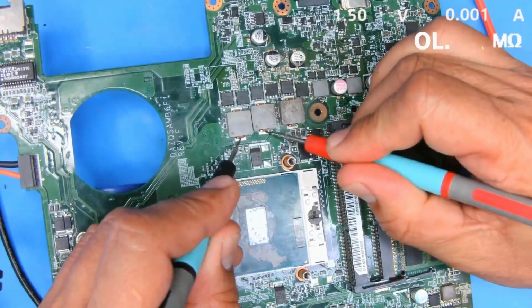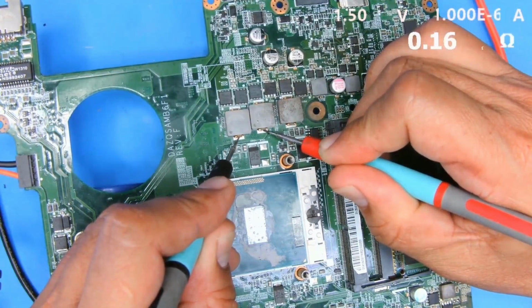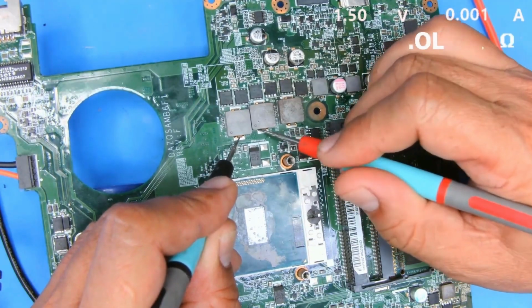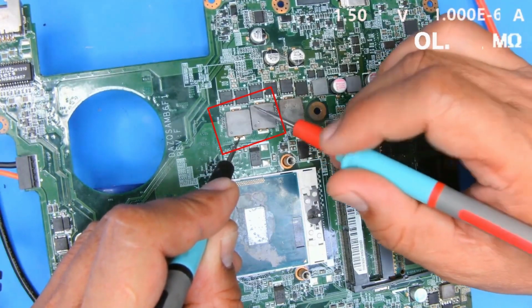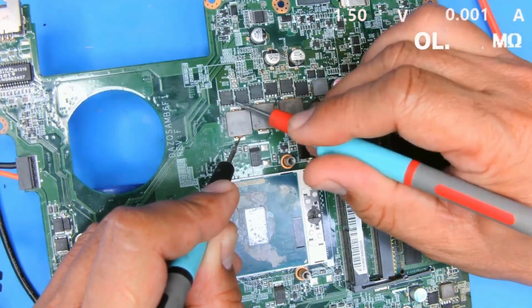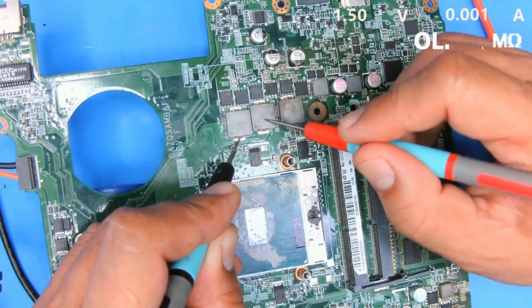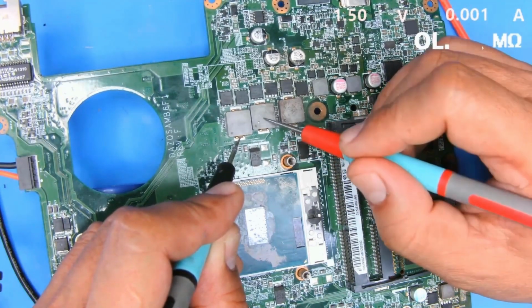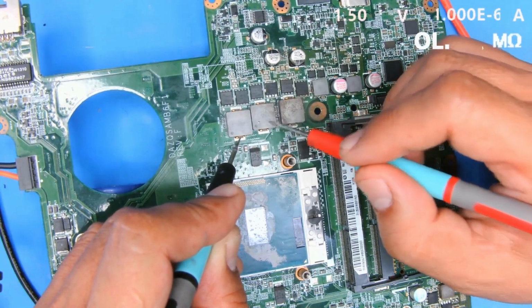If I use the meter to probe at the end of this set here, see, it reads 0.15 ohms. That means these 2 coil sets are connected in parallel again. Therefore, right now, it has to be in this group, these 4 components, but I don't know which one it is yet. This is still a small case, there are only 2 coils, but let's say there are more than this. If there are more, then there will be more points where the high-side MOSFETs are shorted, several of them.